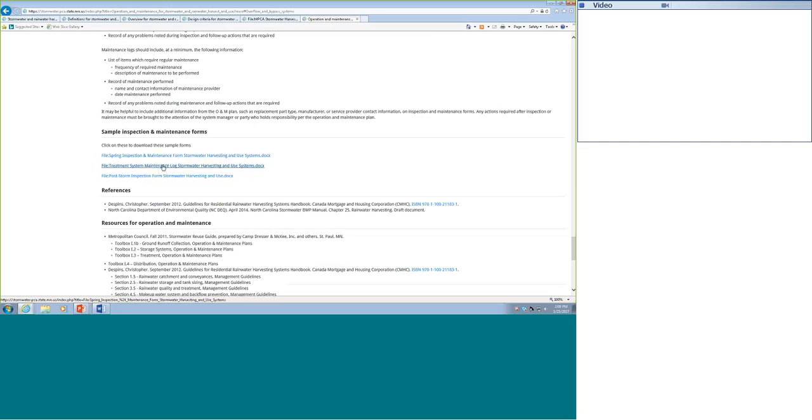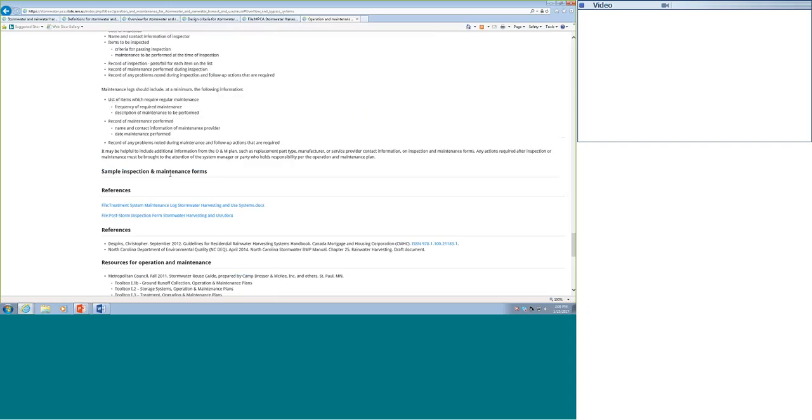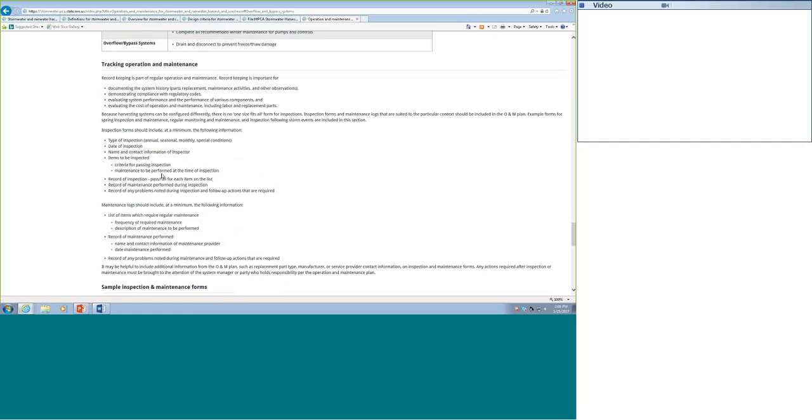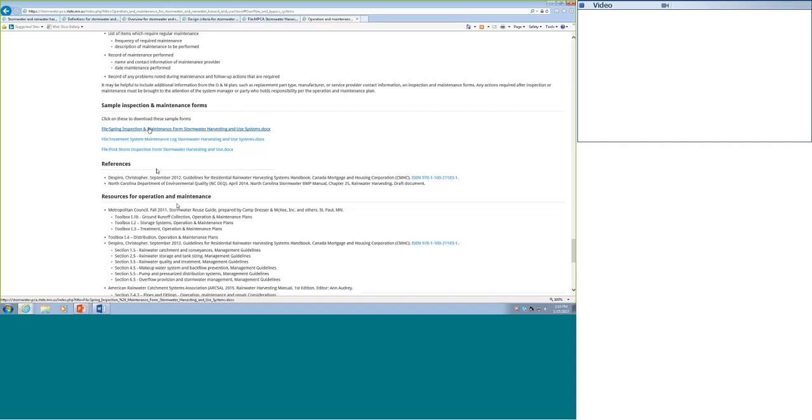Yeah, or even as simple things as people not really operating the tank very well, so a tank sitting there full that receives another rainfall and just overflows is really a BMP that's not functional. So just making sure that there is someone on top of it, you've got a bit of a water balance that you're trying to manage here, so making sure that the system actually is operating as designed, so that as the water is captured, it's also being used, so that then it's ready for the next time it rains. So simple things, but it's a little bit more interactive than some of the other passive stormwater practices that have been more common. Very active operation and maintenance.